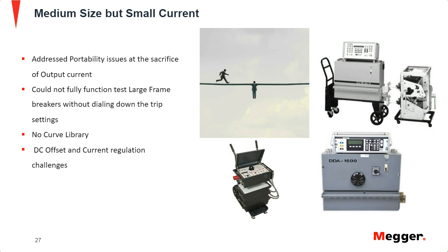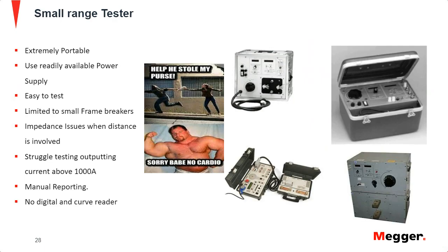So basically, if you have your test current set to 2,000 amps and you're testing for a few minutes, you're going to see that amperage slowly drop to maybe like 1,950, 1,900. So you have to constantly monitor and ramp up the wheel to make sure you keep it at 2,000 and make sure your results aren't skewed in any way. So that is another issue with these older test sets that didn't have any of the software in them yet.